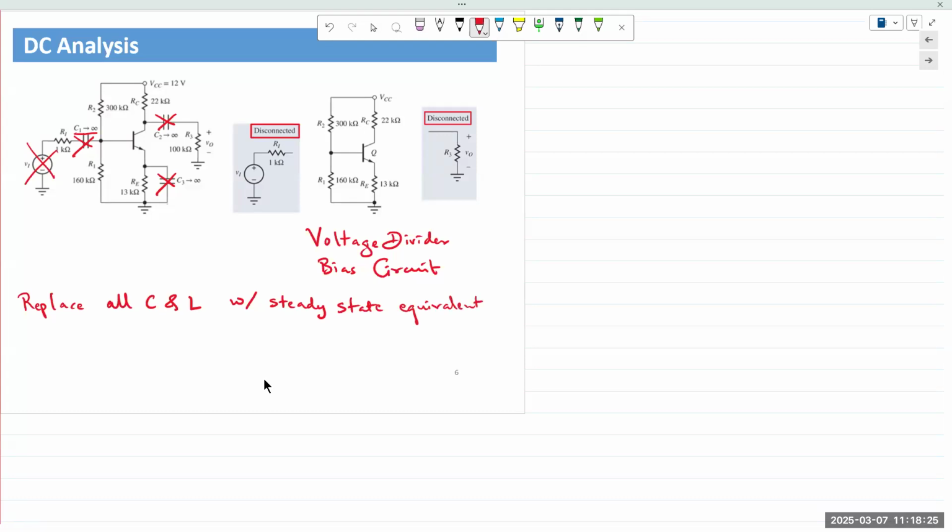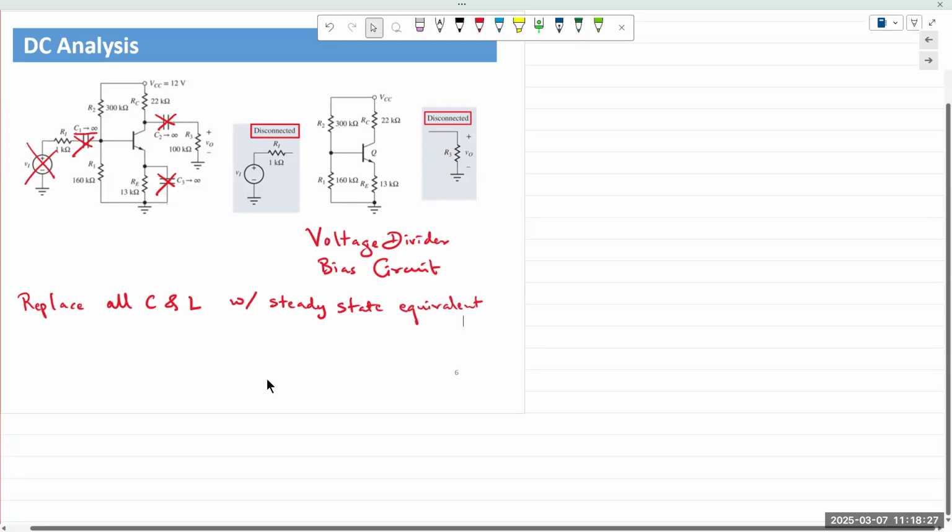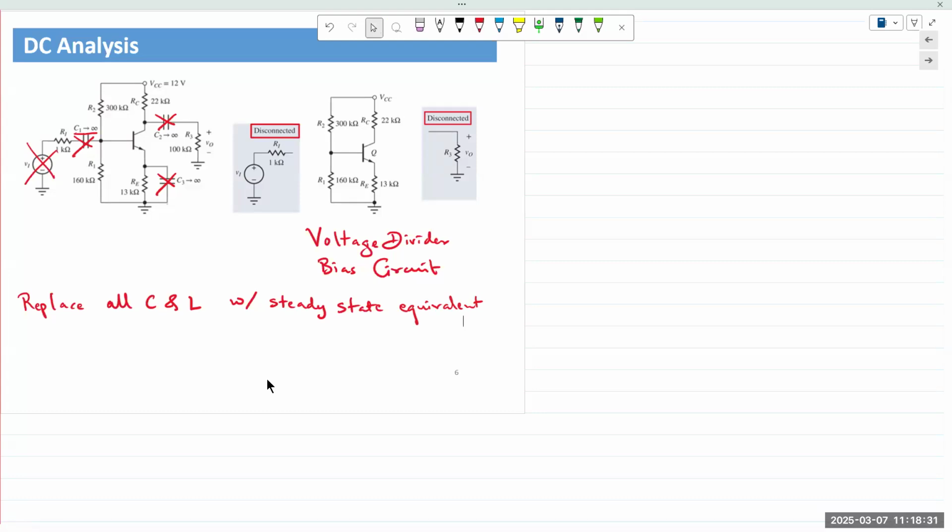So the question being asked is if the operating frequency is dictated by the capacitor. It's actually the other way around. The application dictates the operating frequency of the circuit, and the operating frequency of the circuit dictates what value of capacitor you would choose. As an engineer, you would always have a goal in front of you, and you're trying to reach that goal. So you're working backwards, right?